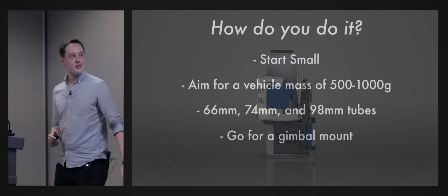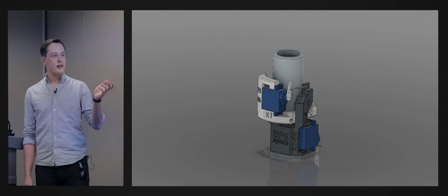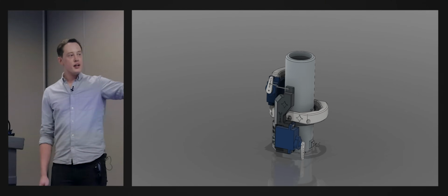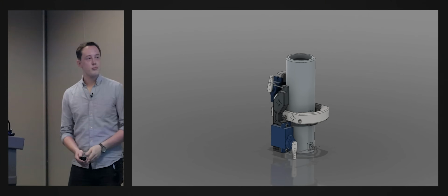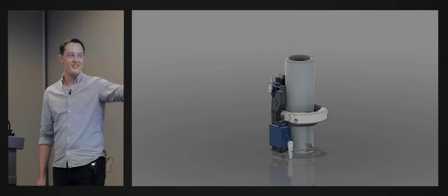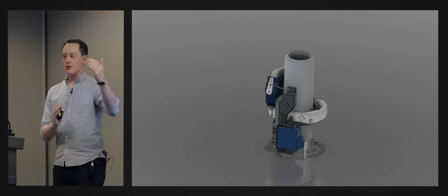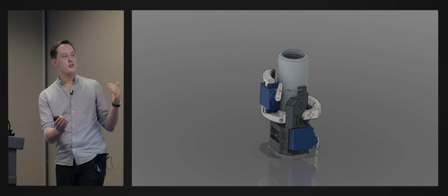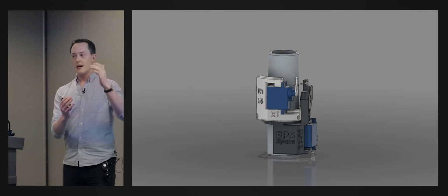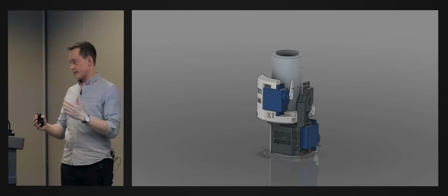All right. So that's how you can go about it. This is the way that I have approached it. This is the gimbal mount that I've done. So you're just gimbaling the entire motor. I've got 2 servos here. And this has similarities with onions and Shrek in that it works in layers. So we've got the motor mount directly connected to that bottom servo, and that works on one axis. But then this top servo is sort of the outer layer of the whole gimbal, and it gimbals the entire bottom assembly, right? So we're decoupling these axes.